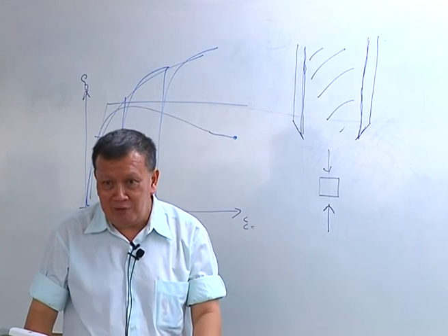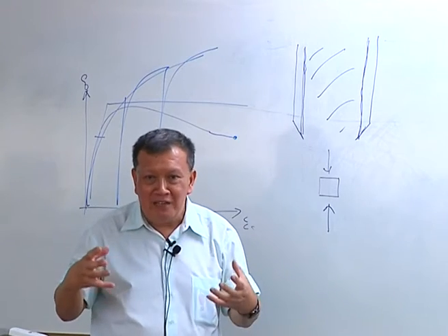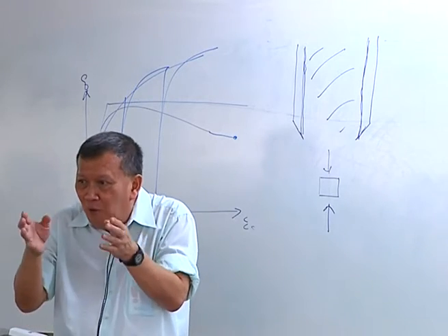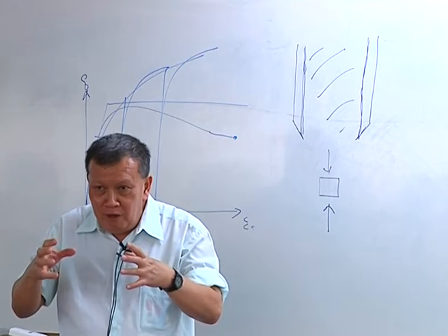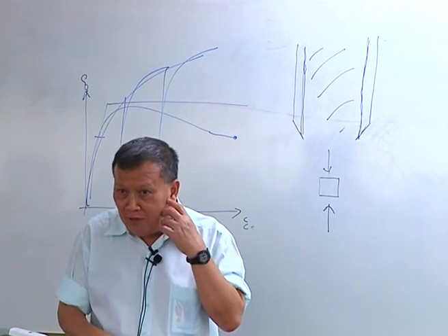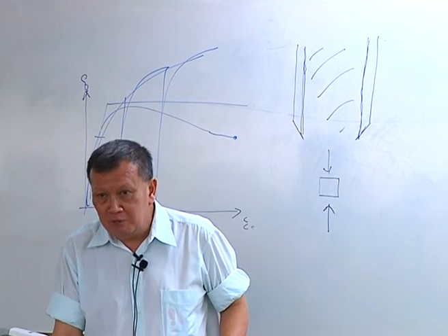So you've got to be careful with that. If you have the wall tightly around the sample, then the tendency to swell is not so much. But if you allow the sample to just clear the wall, then it will start to swell. As a result, over a period of time, when you take it out and test, maybe 3 months later, or if you wait for 1 month or so, you may lose some effective stress. So you've got to be careful with that.